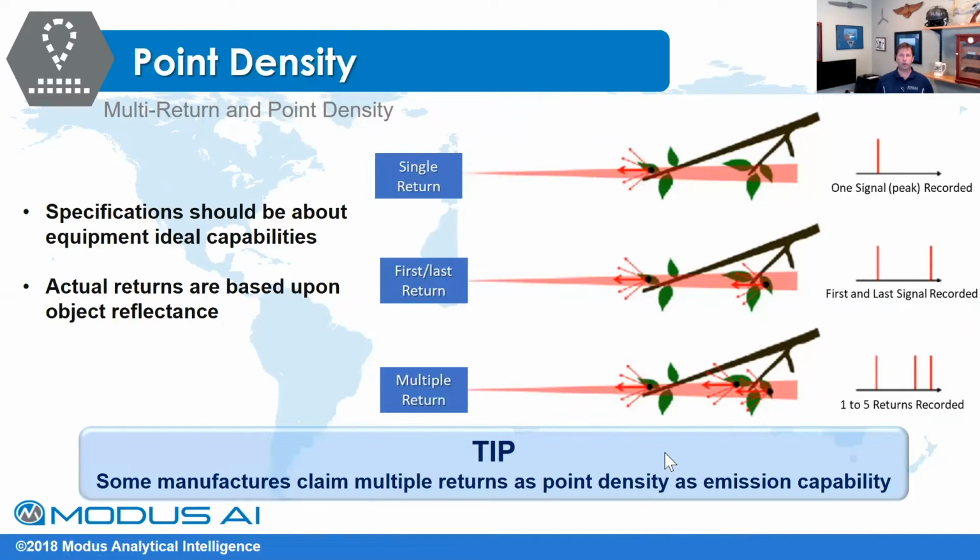And so it depends on, again, that application that you're going to be doing, whether you just need the top layer, which is a digital surface map. If you need to do a DEM, which is a digital elevation map, where you want to pull the surface off and just see the bare earth readings. Or if you really want to get into canopy and feature, you get multiple returns.